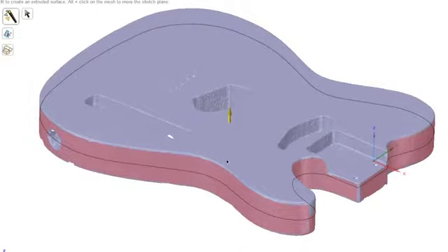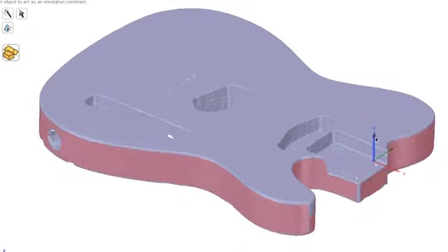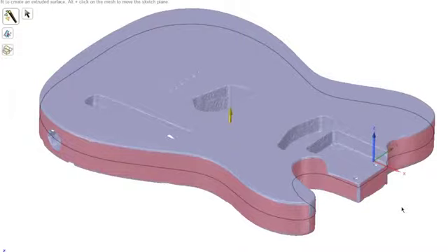You can see that it also has a preview of the sketch in the middle of that extruded area. Right now it's best fitted to the direction of the data that's there, but I can use this option right here, Constrain Orientation, and click on the Z-axis. And that'll make sure that when it does extrude this geometry, it constrains that to the Z-axis.